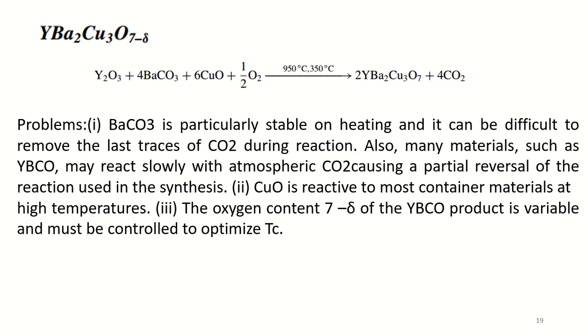The second problem is that CuO is reactive to most container materials at elevated temperatures. The third one is the oxygen content. The 7 minus delta of the YBCO product is variable and must be controlled to optimize the critical temperature.